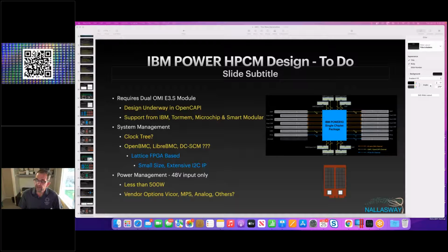Hey Todd, that's the Lattice one, right? LTPI. Lattice has an implementation of the LTPI interface. Yeah, they showed it at the last conference. But in general, it's just a specification that says how you do this. Yeah. It stands for LVDS Tunneling Protocol and Interface. So you take all of these parallel things that you would want to do on the BMC, skinny them down, serialize them across that LTPI interface, then blow them back up, and then on the HPM board do what you need to do.